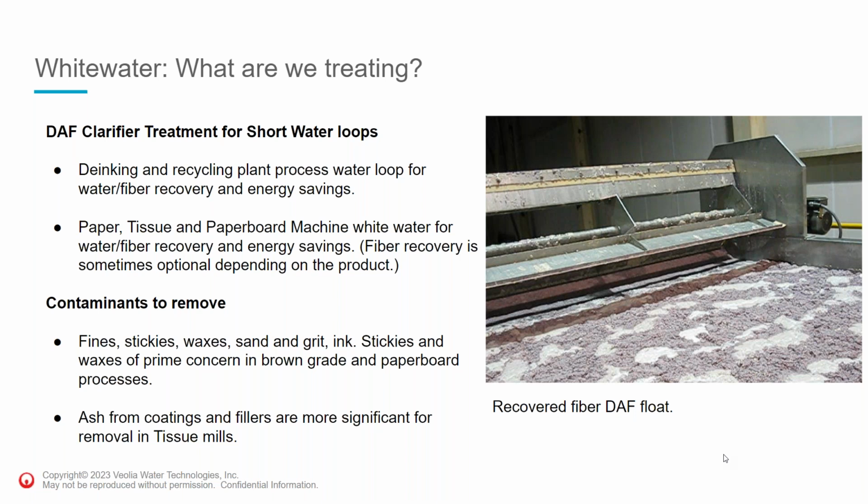For example, many paperboards will try to recover as much fiber as possible, and where there are multiple layers, paperboard manufacturers can take advantage of putting the lower quality fibers, maybe to some extent finer material, into filler layers or bottom layers so they can hide away some of the recovered fiber that comes off the top of a DAF clarifier.